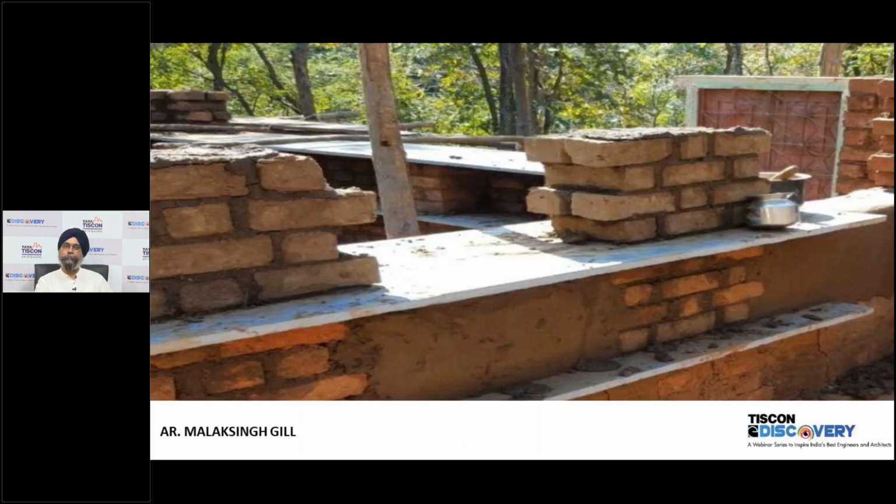This is the walls being made. You see the slabs which later act as storage, but while construction act as stiffeners. And in between it is only mud, the cob technique, which you saw in Vidarbha in the Wardha project, it was 3 feet thick, but here because of this specific design, they are just 9 inches thick.